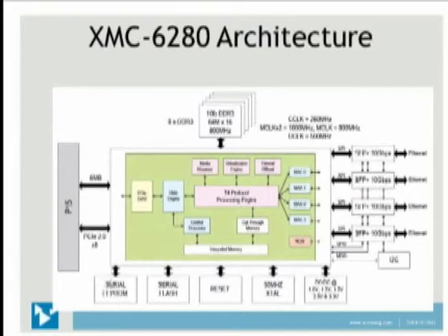And then we have our serial EEPROM. This is where we store our configuration data for all of the PCIe information and the ASIC as well. Then we have our serial flash. This is where the ASIC firmware is stored. Our reset runs off of a 50 megahertz crystal. And then we have our DC to DC converters, which convert 3.3 volts and 5 or 12 volts from P15 to 1 volt, 1.2 volts, 1.5 volts, 2.5 volts, and 3.3 volts, which are all used by this ASIC.